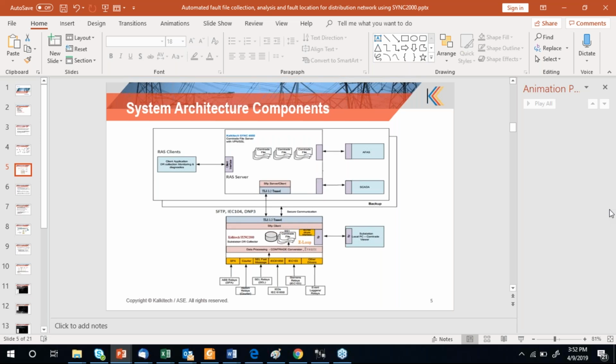And this is based upon the substation level. This file will be available on the event file, and this is pushed to the central system based upon the events which we collect. But other protocols like SPA, Courier, everything is coming from the relay in a totally different format. So what we need to do is, the user needs to sit and map the event number to the actual description and what is the change, and once that is done, it enables an automatic description scenario to be exposed to the center.